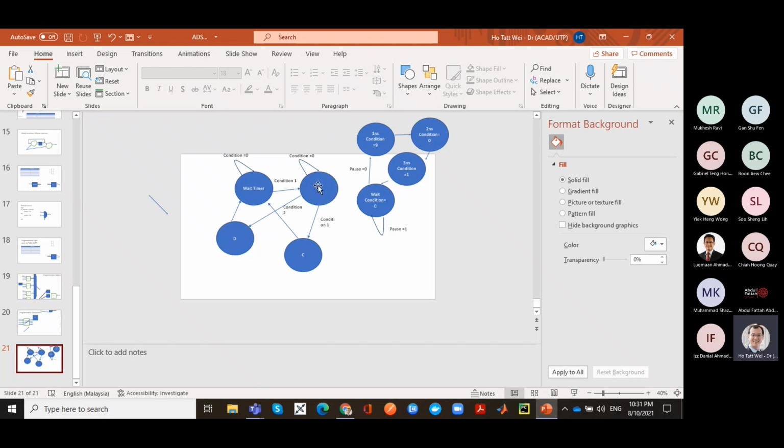Whereas if you were to combine this as a wait timer 1 nanosecond, wait timer 2 nanosecond, wait timer 3 nanosecond, it's a little bit more difficult for you to test only a part of this whole state machine, right? So these are just some of the examples, and a way for you to think about how to simplify your reasoning. This is what I call nested state machines.